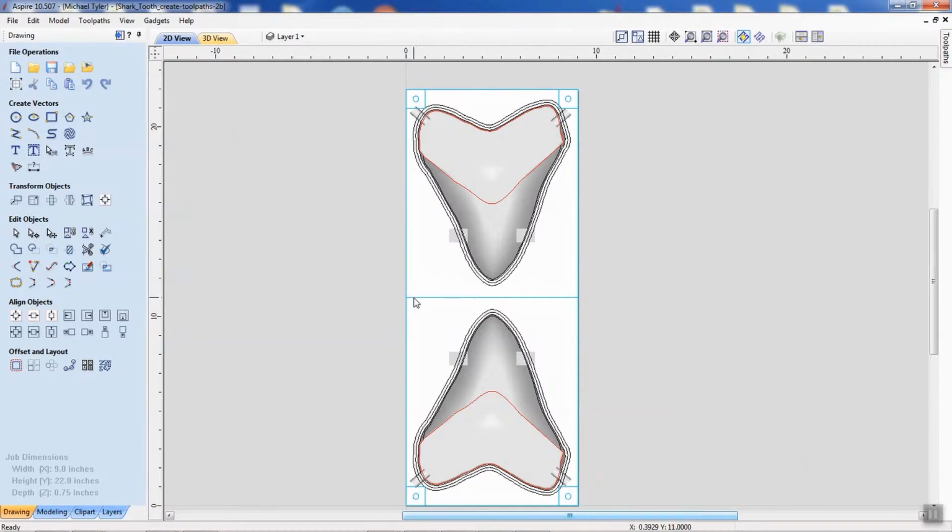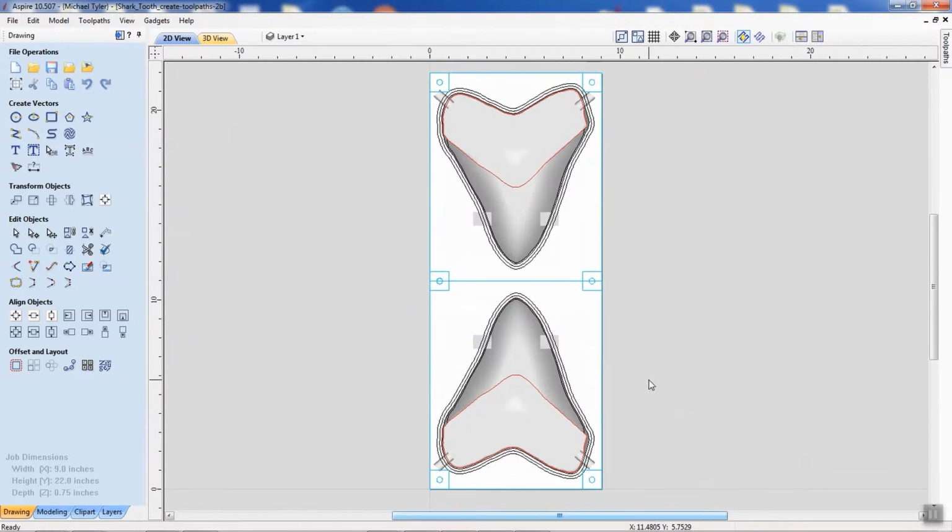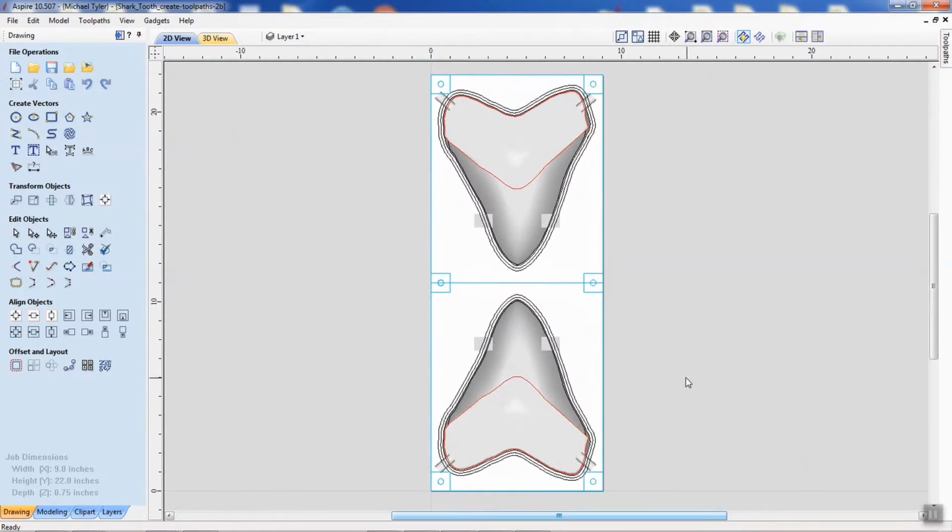And it looks like I might want to have a couple screw hold downs here in the middle too. So I'll just make a copy of this. I'll hold down Control and Alt, and I'll drag this up to the center, and that snaps. Make another copy on the other side, Control Shift H, and there I've got all my hold downs. So that pretty much takes care of our layout.